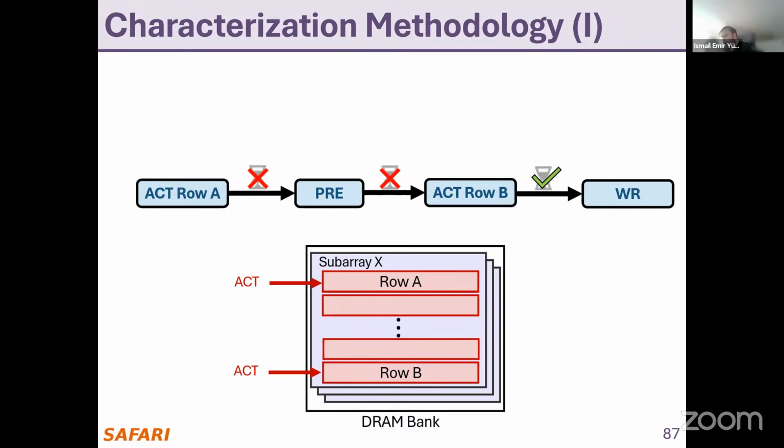In a normal operation, you give the row address as an input for activation. But for write, you don't give the row address, you give the column address. In DRAM, when you issue the write, it just writes the activated row in that bank. So here, it's the same. When you activate multiple rows and then issue a write, it will write to all the rows that are activated.